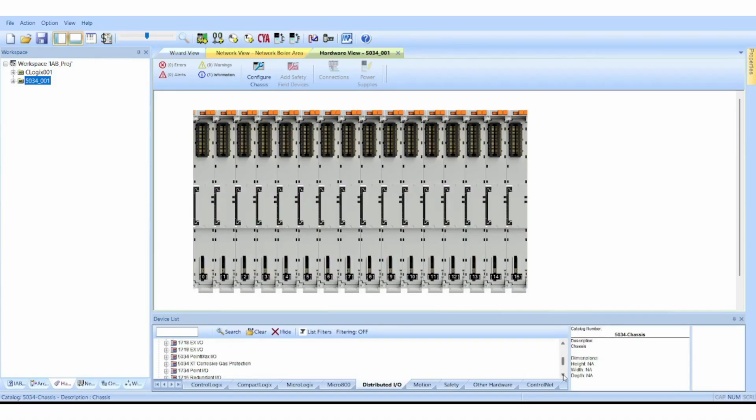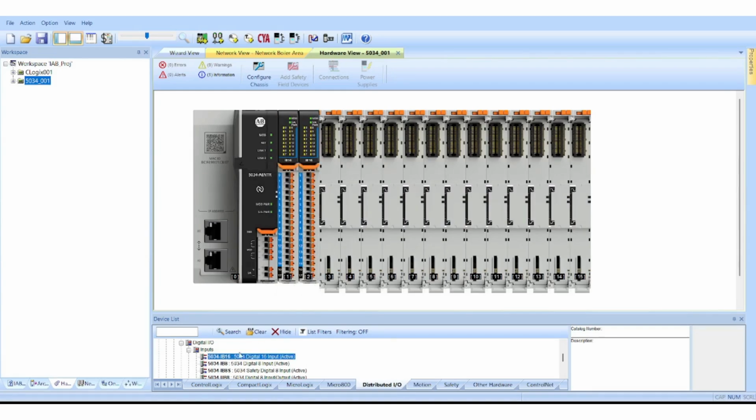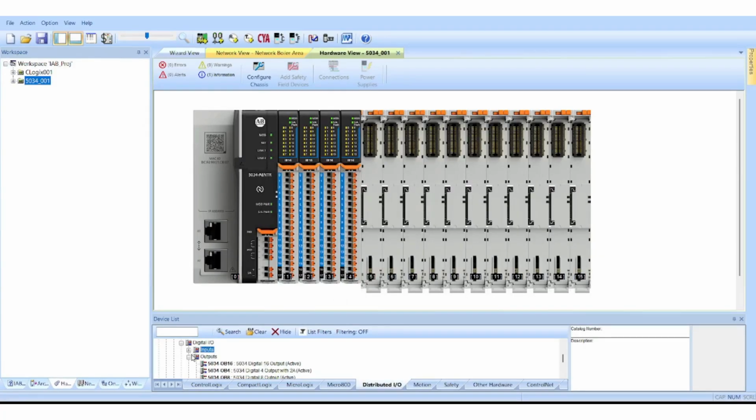In a machine application, sequencing, motion control, servo synchronization, local I/O, drives, and other functions may be very tightly coupled. In that situation, a single high-performance controller is often the cleaner architecture. If additional memory is required, selecting a higher capacity controller, such as an L84E or L85E, may be more appropriate than unnecessarily dividing one integrated machine application across multiple processors. So the important point is this: the best controller architecture depends on the nature of the application, not simply on controller memory capacity.